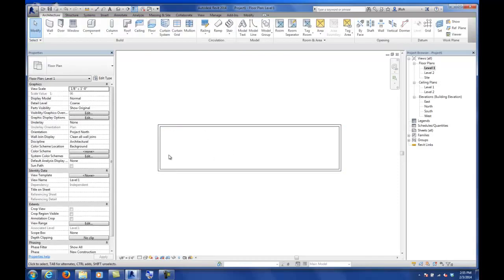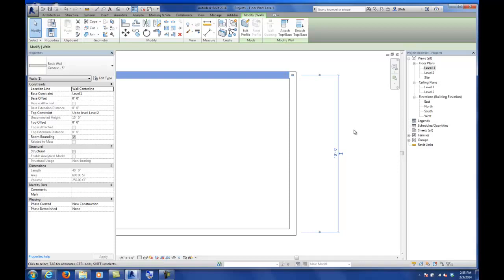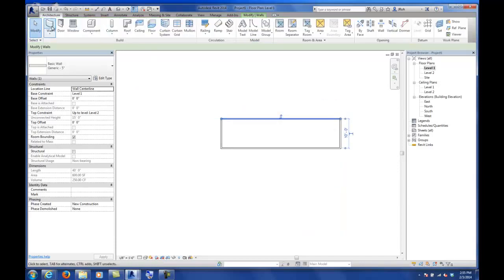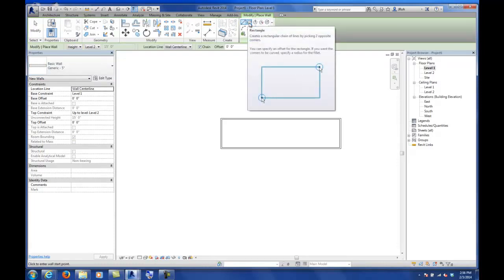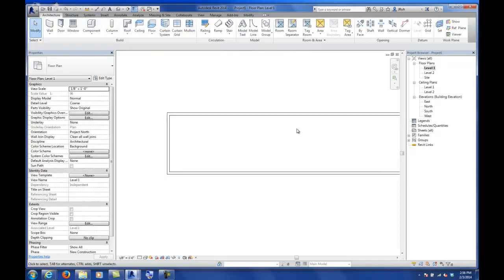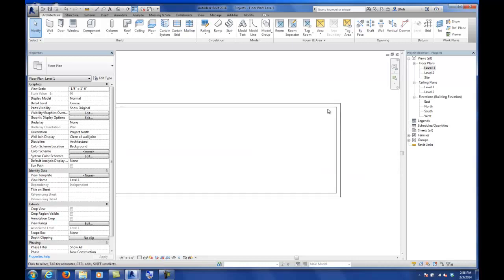So now we've got this block that is 40 feet by 10 feet wide. But notice when we were dimensioning that, what did you use to create the rectangle? I just clicked on Architecture, Wall, Generic 5 inches, and then there's this option in the draw command for the rectangle. And I just did a point and then point. Thank you. Yep.